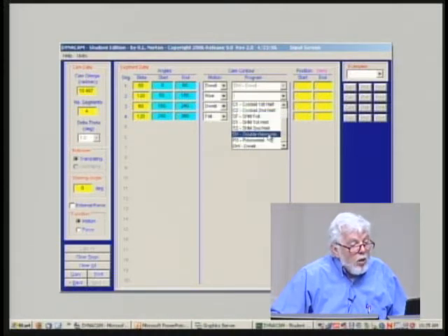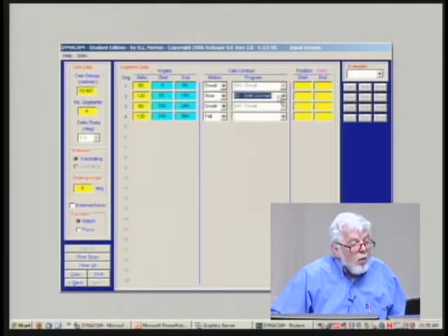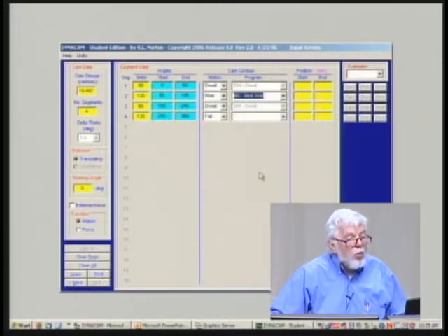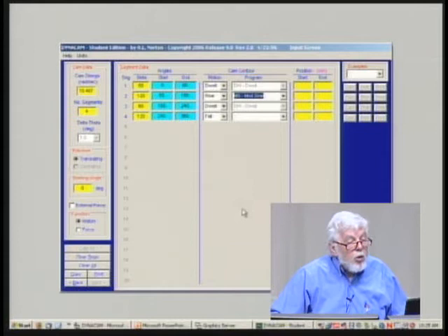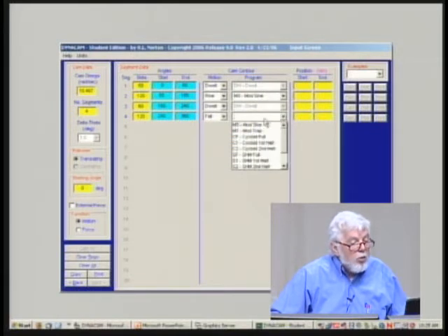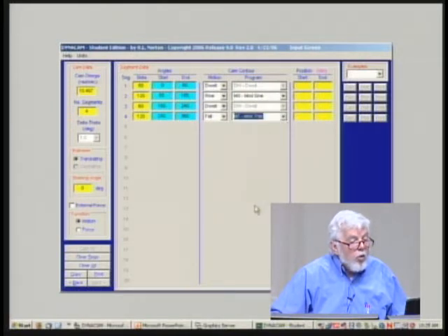A double harmonic is not a choice for a double dwell, so there's only a few I can use here that would be useful. That one is not one. Let me put back something more reasonable. Modified sine would be a reasonable choice here. And just to be different, I'll take a modified trap on the fall, for no other reason than to show you both.